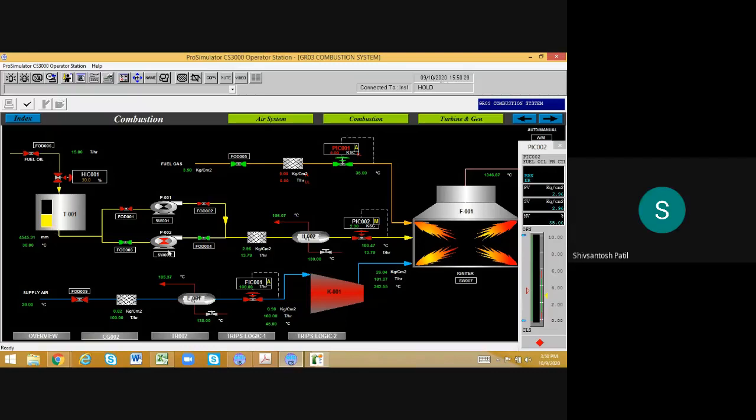Yeah, this fuel oil line is here. When this valve is coming, I have selected the pressure controller here. That's a valve which is manipulating the flow also. So I have manipulated this value. I have changed it to manual mode. At first it is at 50.6 percent MV. I have changed it to 95%. That means I have closed it.